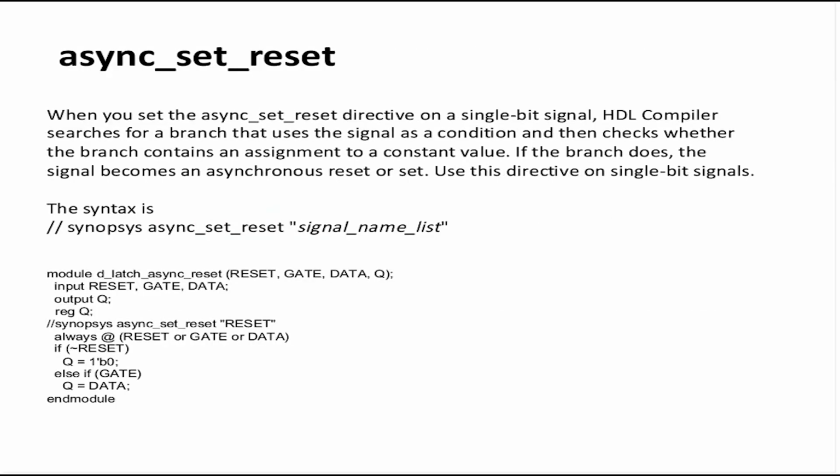Async set reset. Now we saw that there's a rule that if we want to code asynchronous reset or synchronous reset, the first statement should be if. It is very important. As I mentioned before, asynchronous set or reset will be implemented only if you have a corresponding standard cell in your library, a corresponding block or latch with asynchronous set and reset in the library. Only then could you map it.